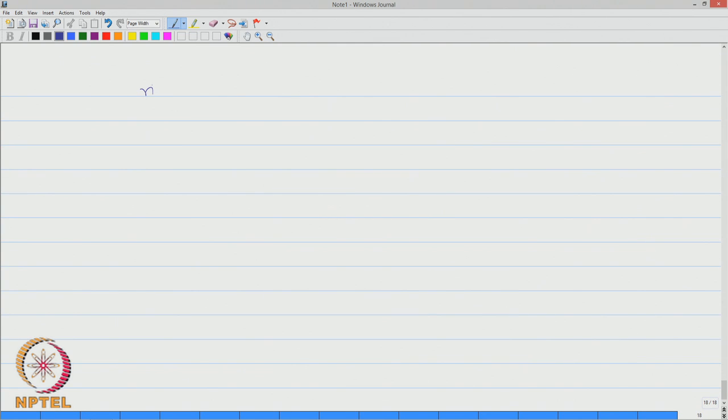So, the rise time for this case is going to be TR, which is L1 by U, which is 2.4 by 398.172, which gives me 0.006 seconds. Time of duration of the loading, which we call as TD, is 0.05 seconds.